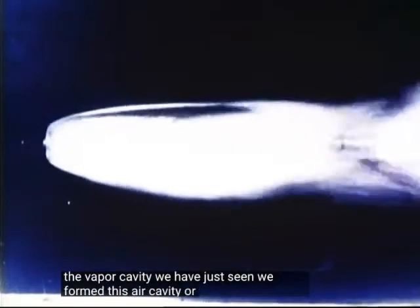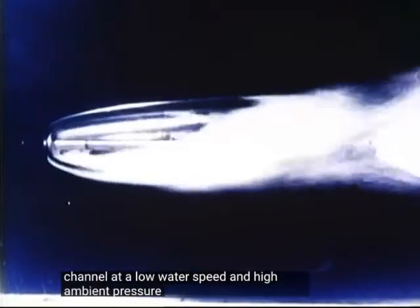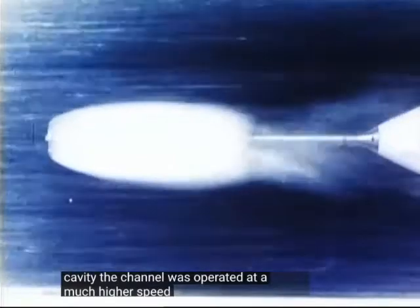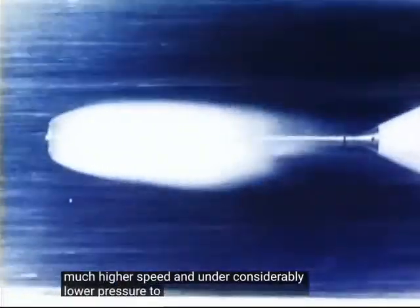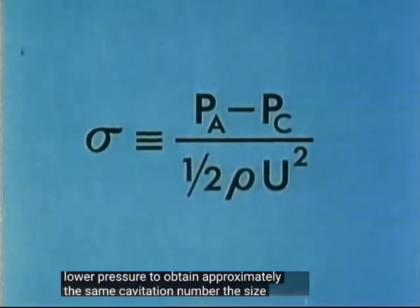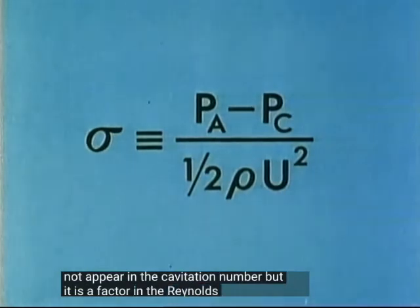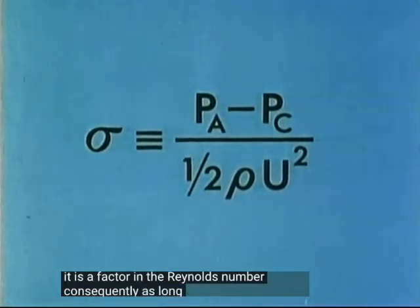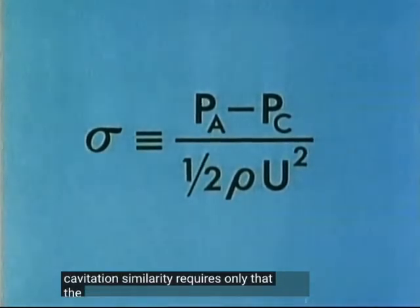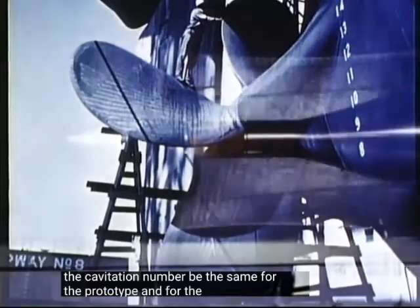We formed this air cavity, or ventilated cavity as it is called, by operating the channel at a low water speed and high ambient pressure. To form the vapor cavity, the channel was operated at a much higher speed and under considerably lower pressure to obtain approximately the same cavitation number. The size of the physical system being studied does not appear in the cavitation number, but it is a factor in the Reynolds number. Consequently, as long as Reynolds number effects are taken into account properly, cavitation similarity requires only that the cavitation number be the same for the prototype and for the model.